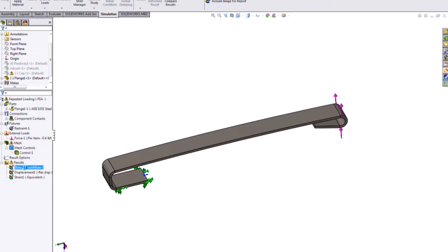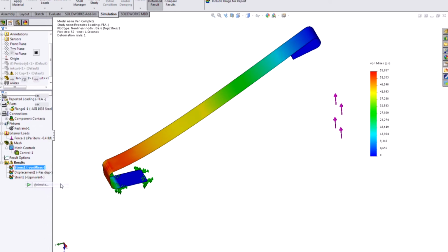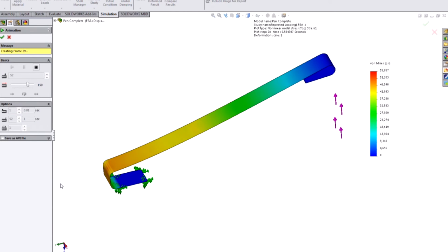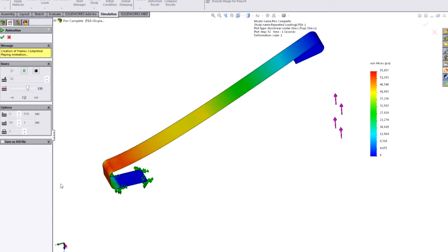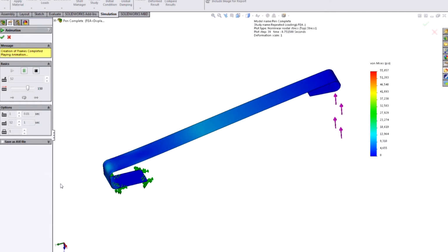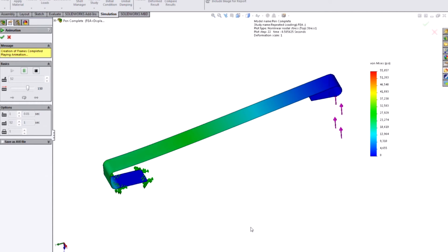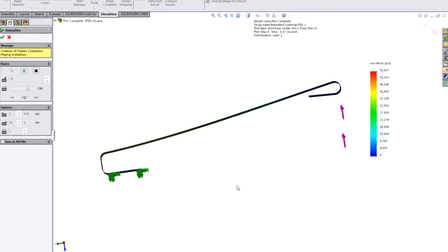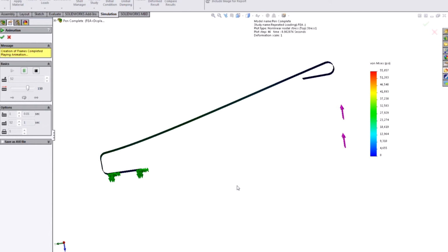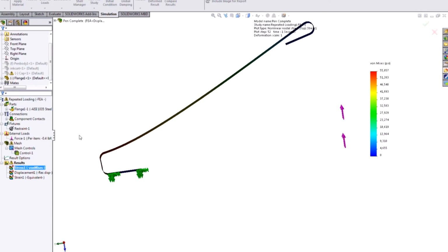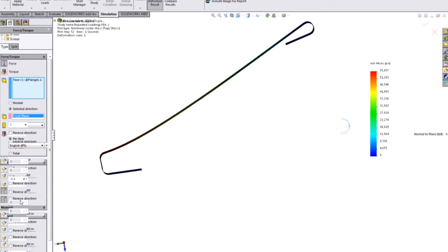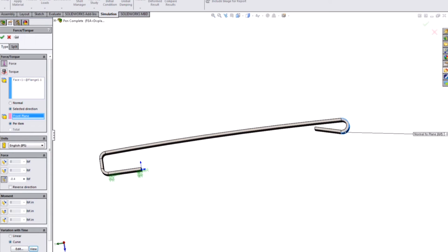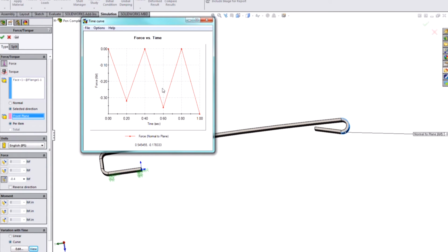And we can even do things like look at loading and unloading phases in the model, see what sort of permanent deformation you might have. Right, so I've got a scenario here where I'm basically applying 3 sets of loading. Each one deforms it a little bit more until we get to a final phase. Just to show you, here's the loading history that this is based on. Slightly increasing load each time.